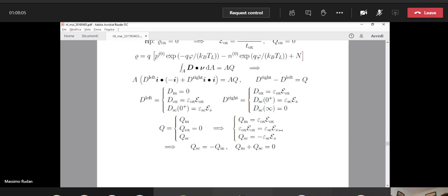So the surface field on the semiconductor side is almost exactly 3 times smaller than the oxide field on the other side. So we have a discontinuity of the normal component of the electric field that is due practically only to the difference in the dielectric constants because there are no charges around in this calculation, near the surface.